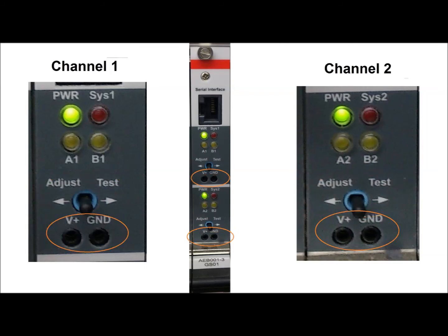The V+ and ground connections are where the wheel sensor can be monitored by connection of a multimeter. The voltage measured at this point is measured over an internal 100 ohm resistor. Dividing the measured voltage reading by 100 will give a current reading. Therefore, a voltage reading of 500 millivolts, which is the normal, equates to a current of 5 milliamps.